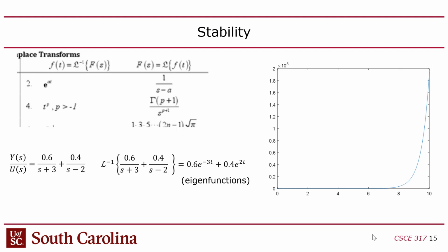This is not the differential equation. This is the transfer function. So this is built in. What's already built into this inverse Laplace transform is our independent and dependent variable, right? But you might say, well, wait a minute, I only see one. I mean, you've got time, right? Well, because it was the raw transfer function, what it really is is the impulse response.